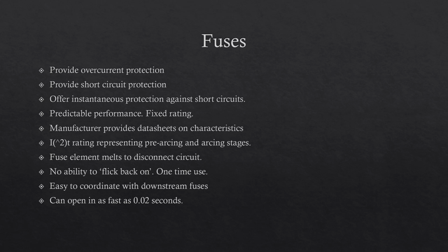It could be to do with an issue with the load. Maybe a motor's failing, or it could simply be that the circuit's not designed correctly, or something was plugged in on a circuit which shouldn't have been plugged in, and it started to draw excessive current.